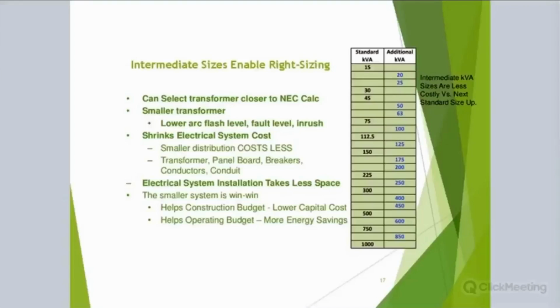That's a 50% increase. But if I know in the real world that the 150 kVA would have had 22 kW worth of load, now instead of being 15% loaded on a 225 kVA, that's only 10% loaded. So therefore your losses are going to go up because the loading went down.